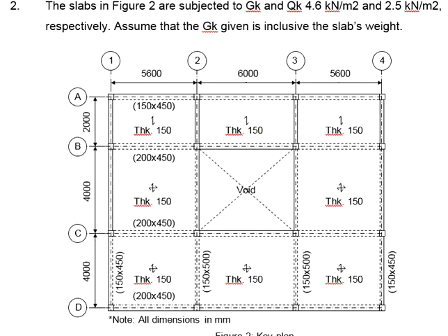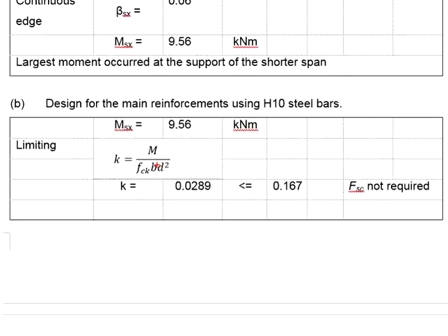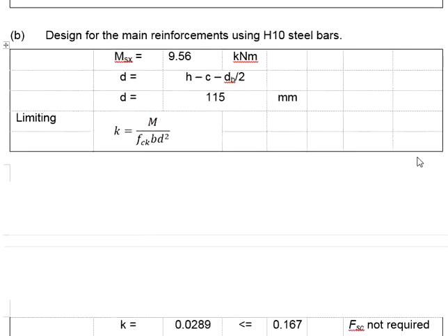For a typical large member, we will take the width on the basis of 1 meter width. That means the b here will be taken as 1000 mm. As for the d, it is the effective depth. The effective depth refers to the distance from the top of the slab to the centroid of the reinforcement.